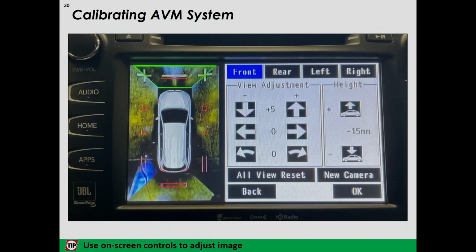Now, earlier I talked about that center line to the vehicle and how critical it is. I've got the camera calibration actually shown on the center display of a Toyota, and I want to show you what that looks like with those crosses there. So when we're calibrating that camera, we're going to adjust that fisheye or wide angle camera so that they mesh properly going to those crosses. And so this is going to be where we actually just adjust the scaling of this camera so that it meshes perfectly with the side ones. And then we have what looks like a good 360 image, only because we're meshing all of those camera angles.